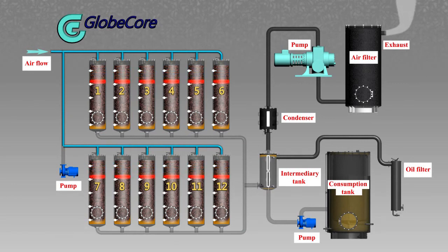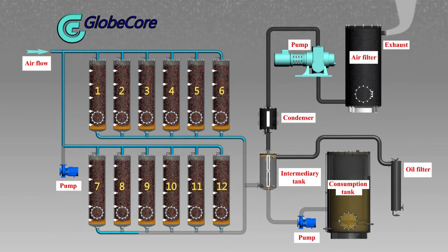The vacuum pump creates the airflow for sorbent reactivation. All oil decomposition products are burned and are expelled from the machine after catalytic breakdown into safe, non-hazardous compounds. Reactivation lasts until the sorbent cools down entirely, which is indicated by cold air in the exhaust system. After reactivation, the control system refills the system from the consumption tank and switches the unit into oil regeneration mode. During sorbent reactivation, the degasser continues to process the oil.